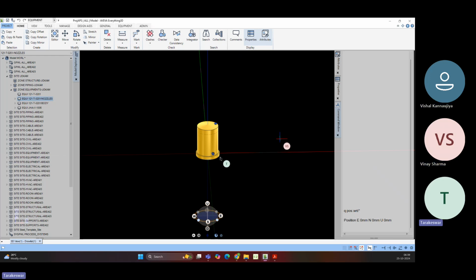And after that, that is technical. And a tool test is also there. See, the tool test will be simple. For example, they will give you one tank, one vessel, and two pumps, and you need to connect the pipe routing. Why are they taking that? Because in pipe routing, what is the sequence you need to follow, especially for the suction line and discharge line, and what kind of support you are using. That they just want to see. That is the most important thing, actually.